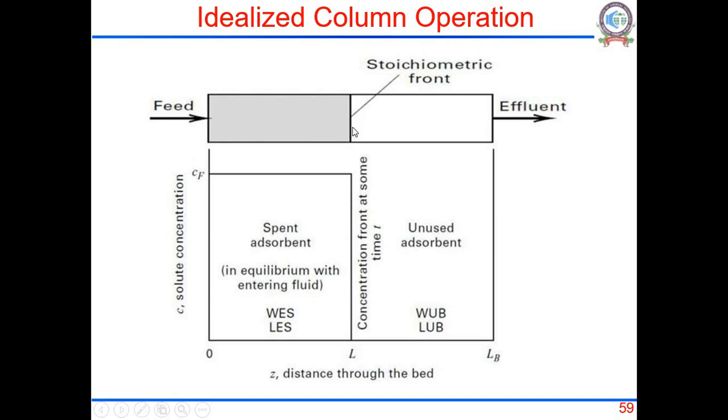If the kinetics are very fast, then this adsorption front will be just a straight line. We will have a clear demarcation between the bed that is at equilibrium with this incoming feed solution and the bed that is free. So in this part, if you plot CF, that is the concentration of the solute, CF is, let's say, the feed solution. So the feed solution concentration does not change till you come to this adsorption front, and then because the adsorption is so fast, it becomes essentially zero, and beyond this part of the bed the concentration is zero.